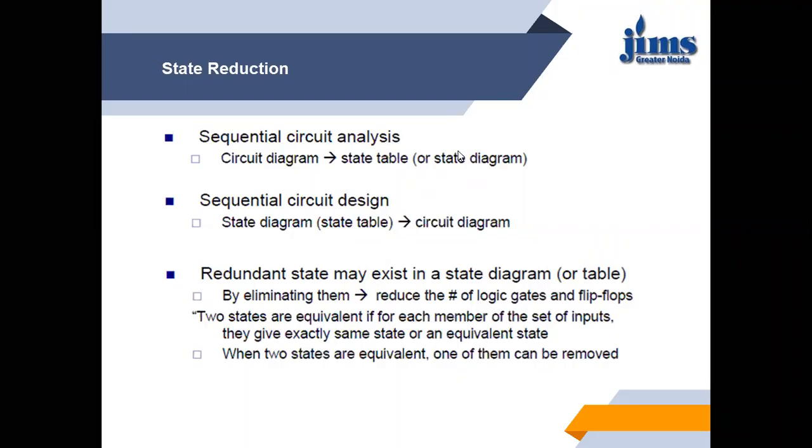So we have to keep in mind every time we are dealing with a state diagram that the redundant states must be removed, and the process of removal of redundant states is known as state reduction. The benefit of state reduction is that we are finally decreasing the complexity of the circuit. We are reducing the hardware, that is gates and flip-flops, and further we are decreasing the cost of our final design.